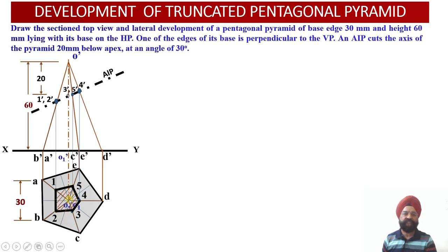Now this portion has been shaded because this portion was sectioned by the cutting plane, and we call this portion the section top view, and it represents the apparent view of the cut section in the top view. And having obtained the section top view, now we need to join the remainder of the slant edges.